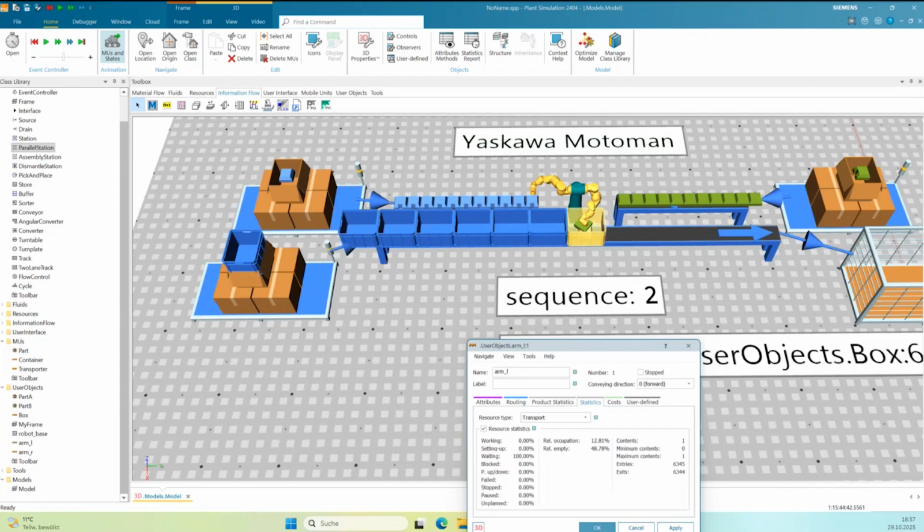Okay. If you want more complex movements for the robot arms, you need more joints. And I have already 7 joints here, but then you need the joints in the robot arm. If you don't have more, then it's difficult to animate this or simulate this. So you can only move in the joints you have in the graphics. And this robot, I have skipped 1 joint. This is in Z-axis of the robot base. And so, yes, if you had one more joint, then you have 8 axes, and this is quite complex already.